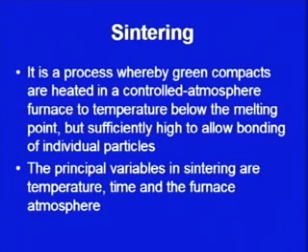Here the metal powder green compacts are heated to an elevated temperature lower than the melting point, so that bonding between the individual particles takes place and the density of the green compact improves. The principal variables in sintering are temperature, time and the furnace atmosphere. Sometimes the furnace atmosphere is required to be an inert atmosphere, and we must also consider the time for which we leave the green compact at the sintering temperature. All these points have to be taken care of when we go for the process of sintering.